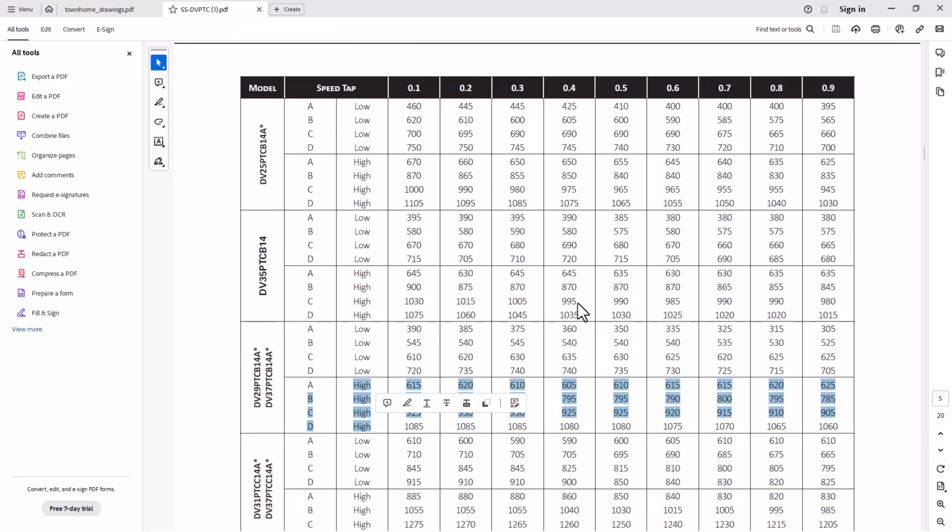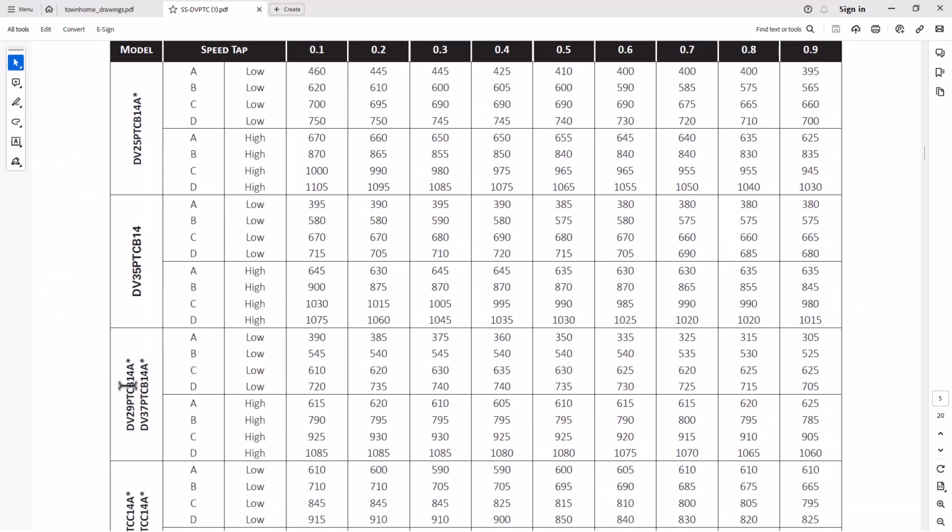Do we have this in the blower data? Let's check for 0.7 static pressure, which is debatable. We can talk in another video about this 0.7 static pressure, because I'm sure a lot of contractors and designers will ask about the 0.5. Leave that in the comments and we can coordinate further. So seeing here, for 0.7 we have 800 CFM. There we go.